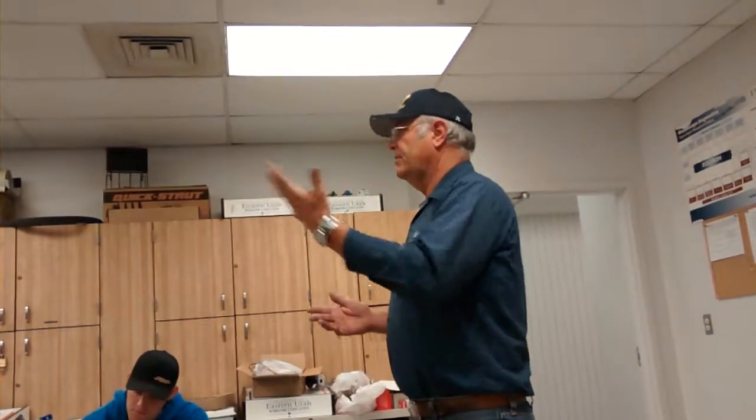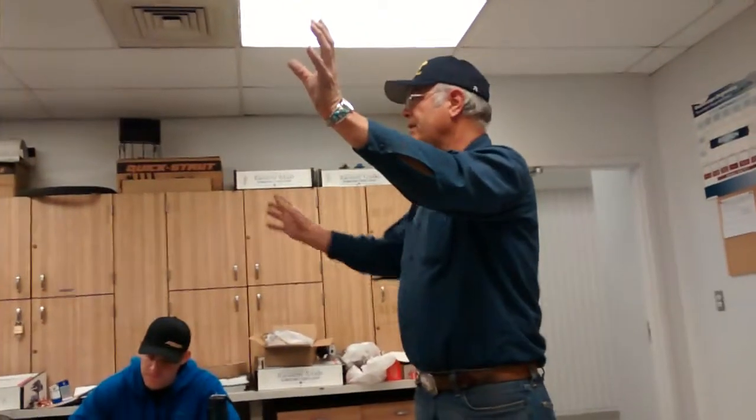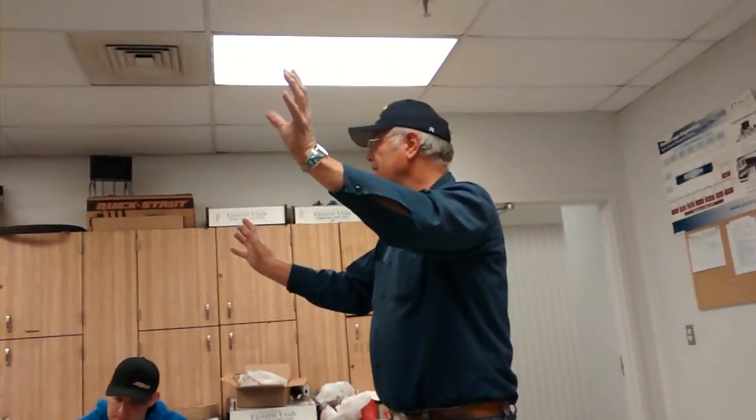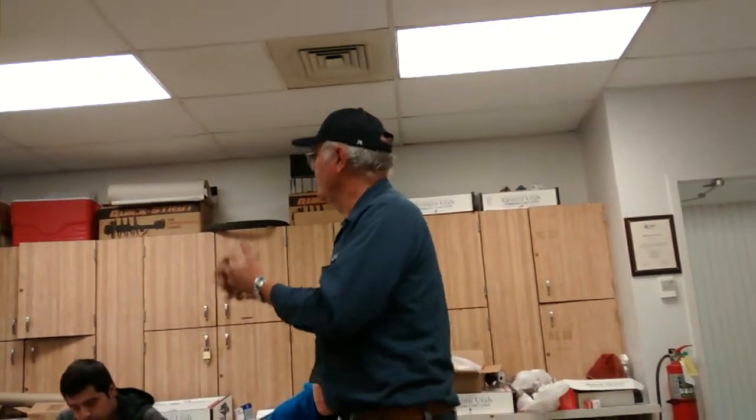You see this all the time in a headlight, for example. You're driving at night and somebody's coming towards you and you'll notice that one light is bright, the other light is dim. You ever seen that on a headlight? Okay. The reason the light is dim is because it doesn't have enough amperage or flow to make the bulb light. And the reason it doesn't is because usually we have a resistance in the circuit, so it takes part of the pressure, the voltage pressure, to get through that resistance, so it can't push the amperage.